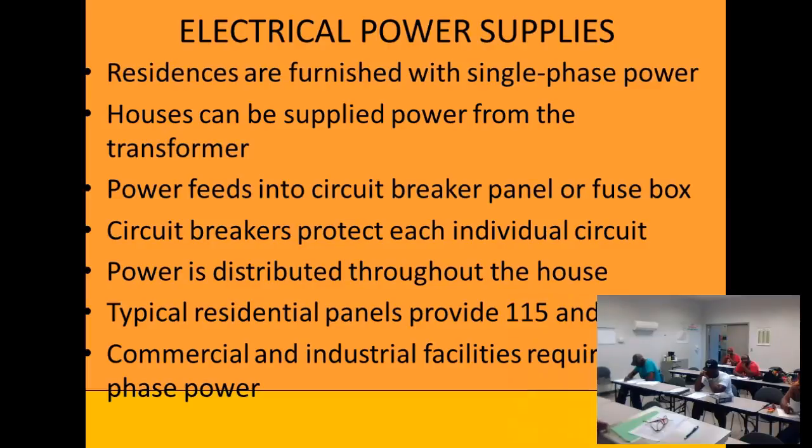Well, what did we just say? Is that single phase power? Yes. Plus or minus 10% for 24 volts. So that would be what, 2.4 volts up or down. And so we would wire this thing up and see if it would come on above or below that. A lot of times it will come on, but it won't last as long. A lot of times, if it doesn't have the proper voltage, it doesn't close hard, and so it might bounce. And so you get an arc across it, and you start having arcs across it, that damages those contacts, softens up the metal, and you have a lot of problems.